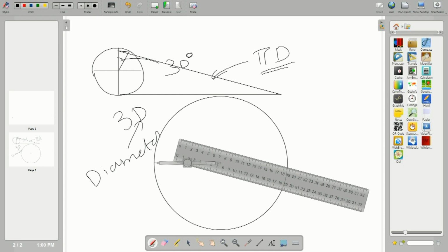Then draw a 30-degree line from the center point, from the vertical to the right side, that intersects the circle. From there draw a horizontal line, which again intersects the vertical line above. Then join both ends, the end of the 3 times diameter line and this point, and that shows the circumference of a circle. This is the method to construct and determine some measurements.